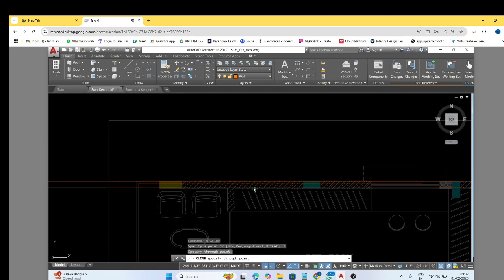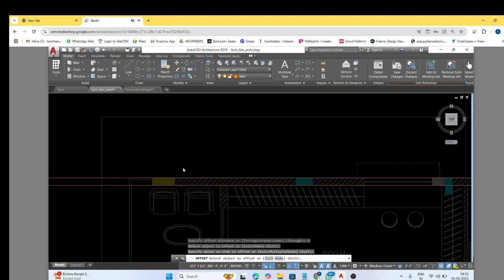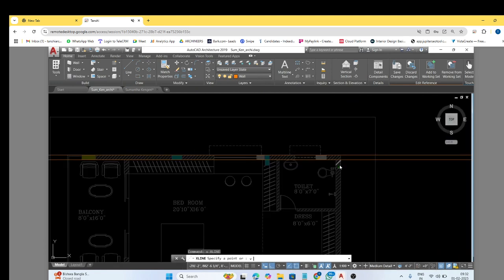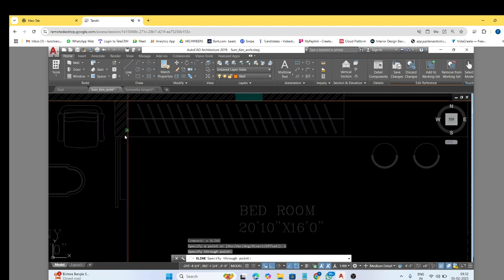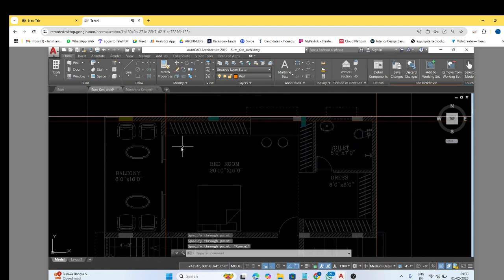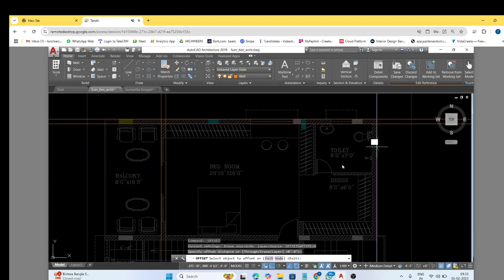So then you just place one X line, and after that keep doing offset and continue the plan. X line, wherever you find it necessary to have vertical or horizontals, because if each time you do X line, you might not give proper 8 inches wall. So one place you give properly, and then after that do offsets and trims, offsets and trims, and that's how you have to work continuously.